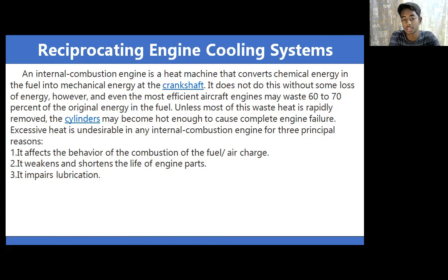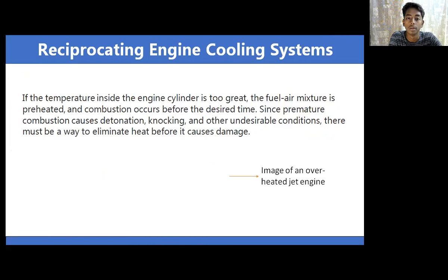Those 3 principal reasons are: it affects the behavior of the combustion of the fuel or air charge. Second point, it weakens and shortens the life of engine parts. It impairs lubrication. So these are the 3 factors which affect reciprocating engine cooling systems. So to the next slide.